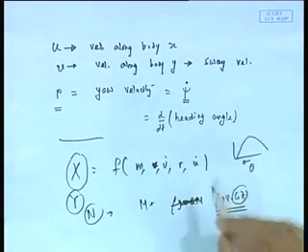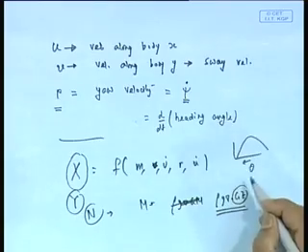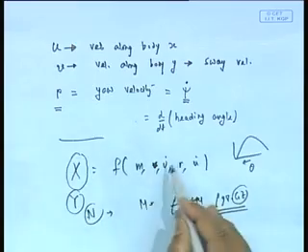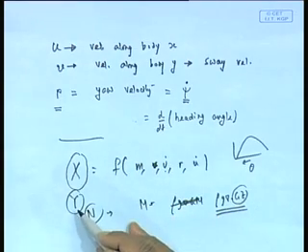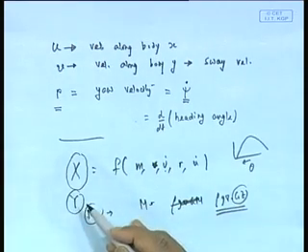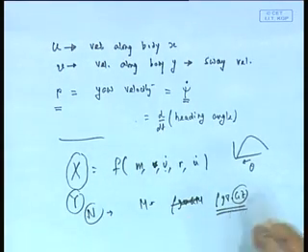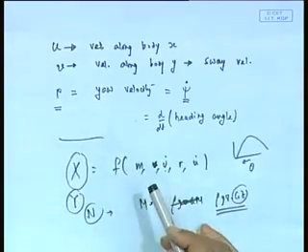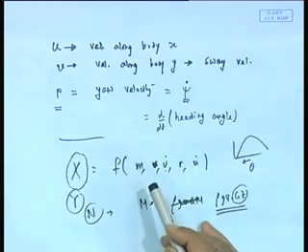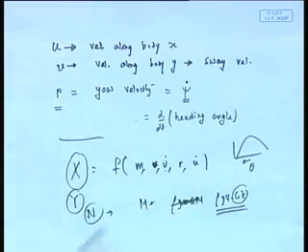Remember that this GZ graph, if you plot, as theta came down, GZ came down. Right. As theta came down, GZ could not have gone up, because then there would have been a violation. So similarly here I have to find out, if v comes down, does y come down or y go up. It is a necessary condition that it must come down in order for it to come to the position, because as I am bringing back theta to 0, my restoring moment must come to 0. At theta 0, my restoring moment must be 0. Similarly here, when my v becomes 0, my y must be 0. If it was not 0, then it would continue to shift. And these are the kind of questions we will be asking and finding out.